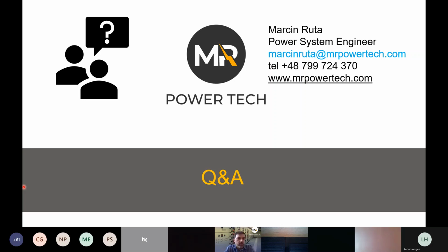That was the one that I mentioned, DGUV 203-077. That's the approach from the European side. Maybe just to give you a bit of comment behind it: with IEEE, you can use IEC 60909. There's no problem with it. Technically, you can even use IEC 61363 for marine, just most of the time it's not used for it. We use 60909 in marine also for arc flash calculation. That's good enough.